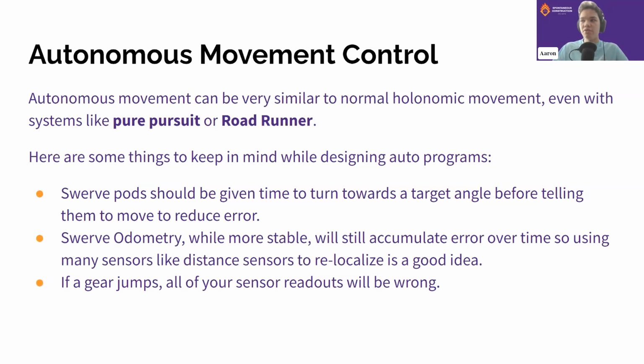Generally, just try to command your robot with very smooth movements using acceleration curves, or just not telling it to move incredibly fast too early. And you should be able to avoid gear jumps fairly often. Also try to avoid going over really rough terrain elements, as they can also mess with the hardware of the gear. But if the hardware for your robot has been built fairly well, this might not be as much of an issue to worry about.